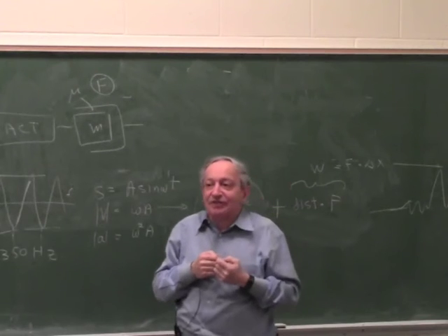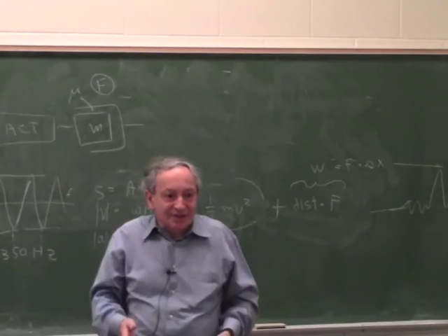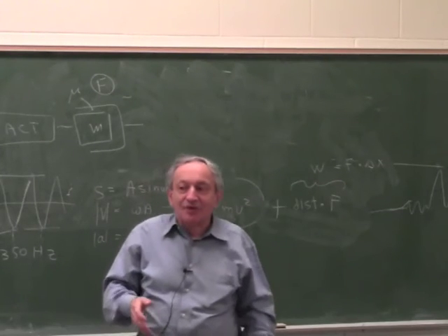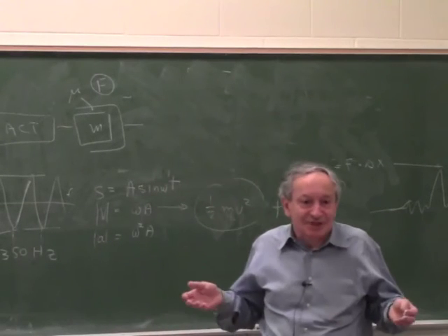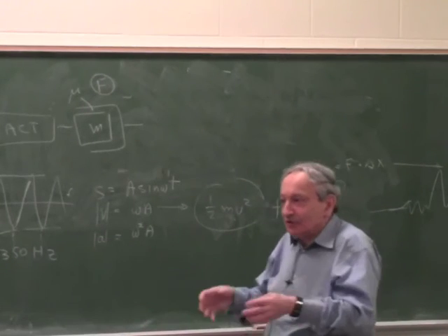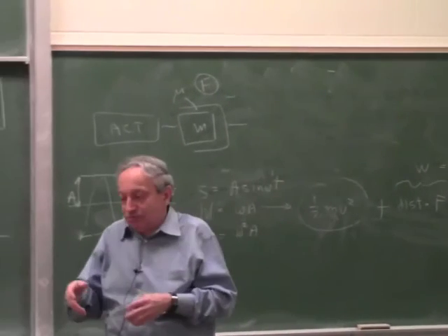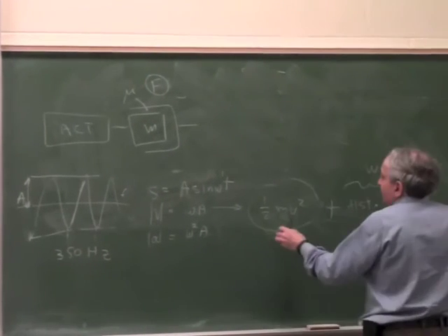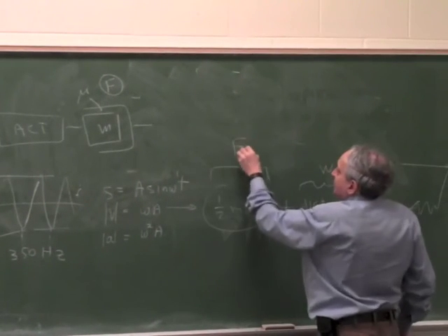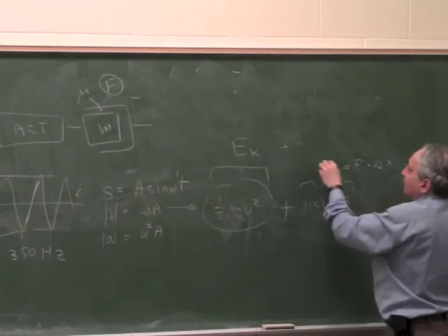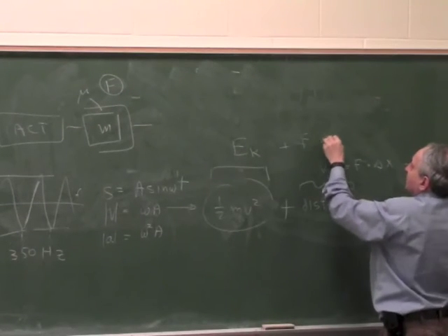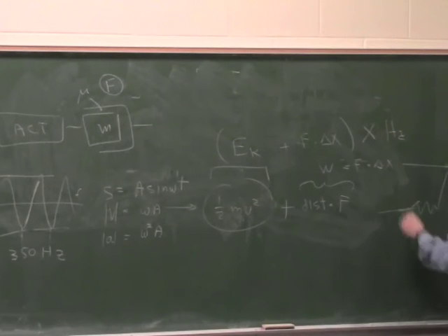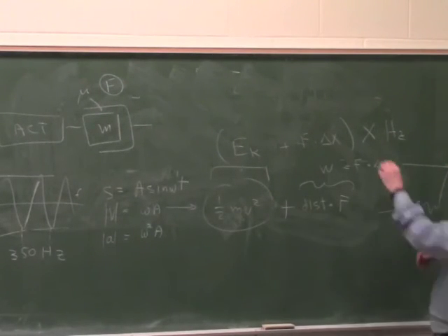Say gravity. Let's say you have a servo which controls an elevator. It lifts it against gravity with a force F. In theory it's all recoverable. But if you don't have regenerative systems, even that is not recoverable. So for small servos, like a machine tool or a disk drive, no energy is recovered. So per cycle, you have the kinetic energy, plus you have the dissipation, F times delta x, and all this is times the frequency, because this is per cycle.